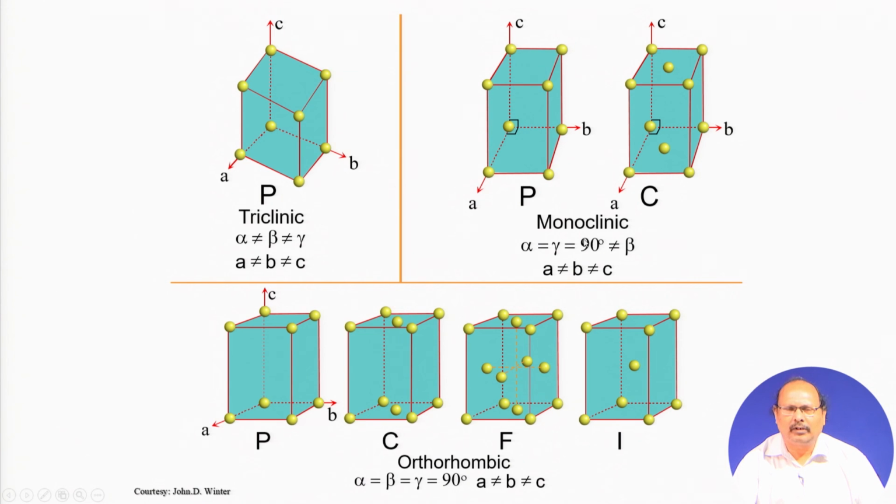In case of the monoclinic crystal system, you have a 3-dimensional lattice such as this. This is also primitive, because lattice nodes lie at the 8 corners, and you also know the angular restriction between A, B and C. So, you know the angle A to C, beta, is not equal to 90 degrees, but angle A to B and B to C is equal to 90 degrees.